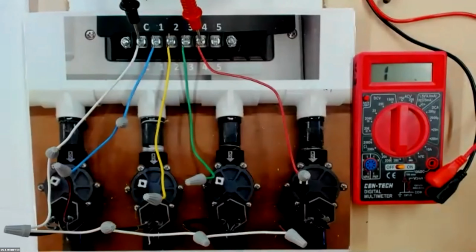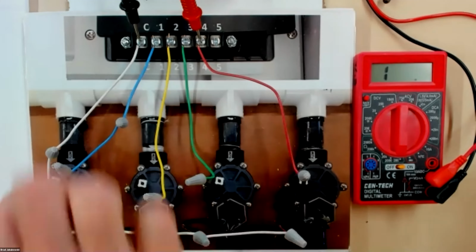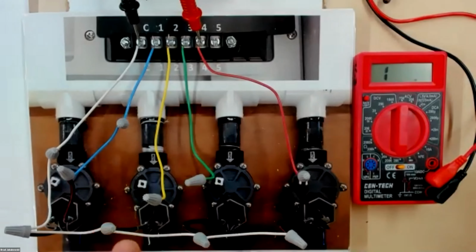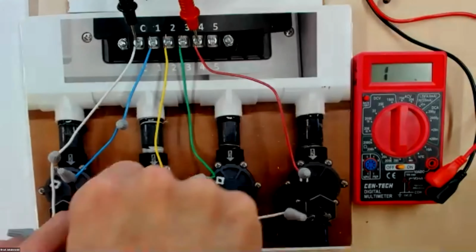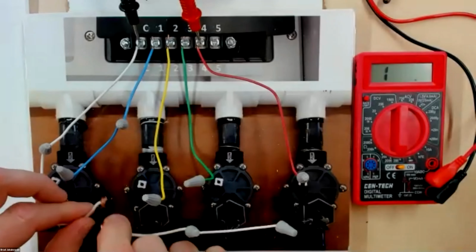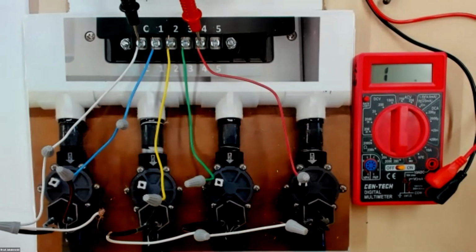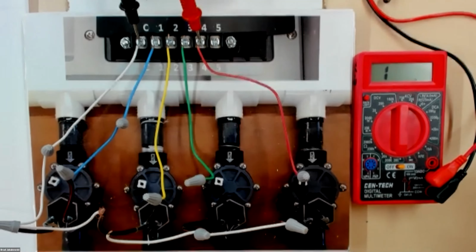And with this one here, we could actually do a number of different ones. We could disconnect the one on the blue, or this one here. Let's go ahead and, off of solenoid number 2, disconnect this one here. Okay, so we're going to disconnect this one here. This is me trying to isolate a common wire after, let's say, the first station or at a different station there.